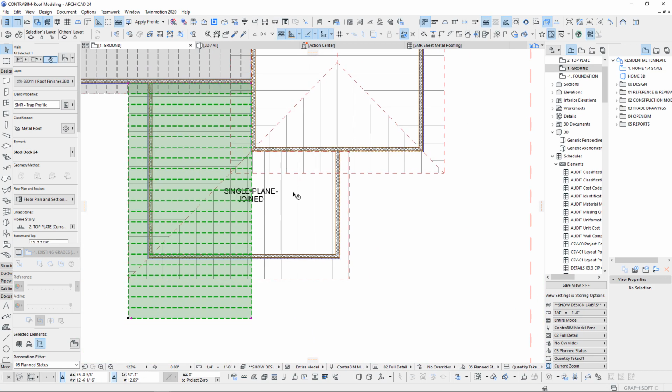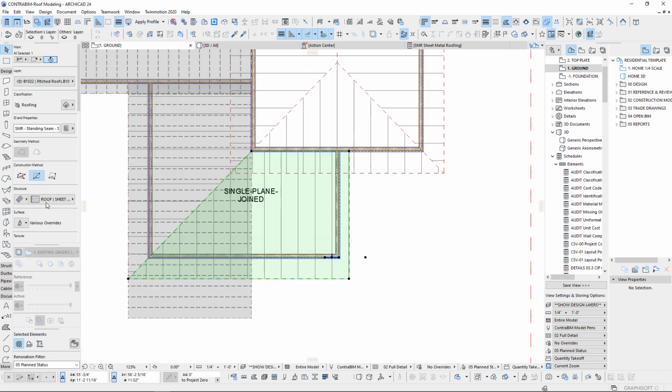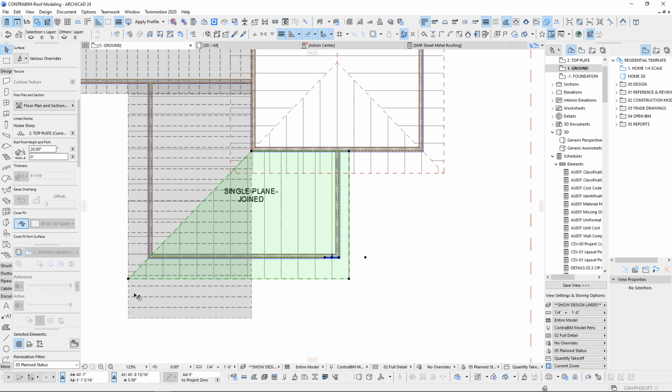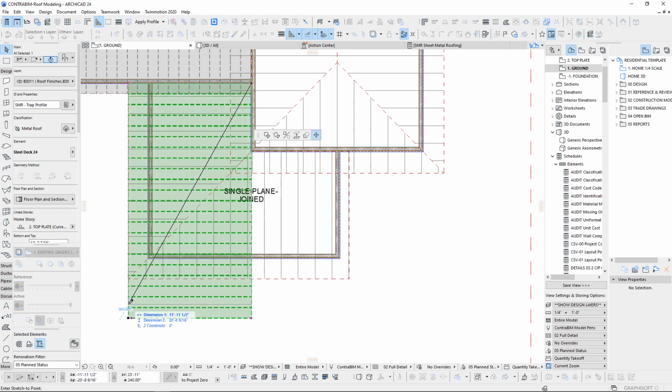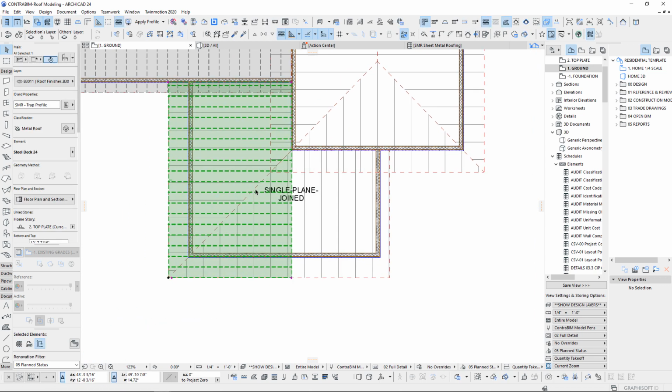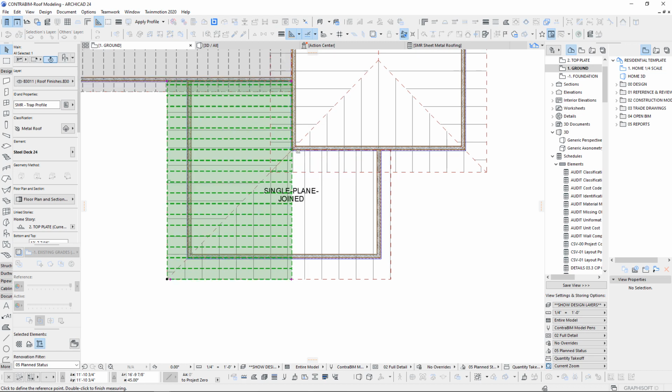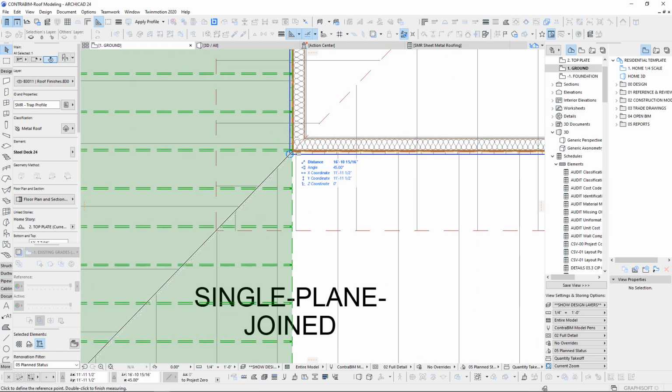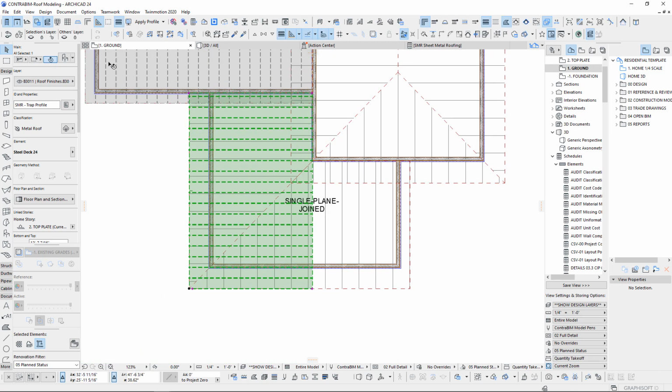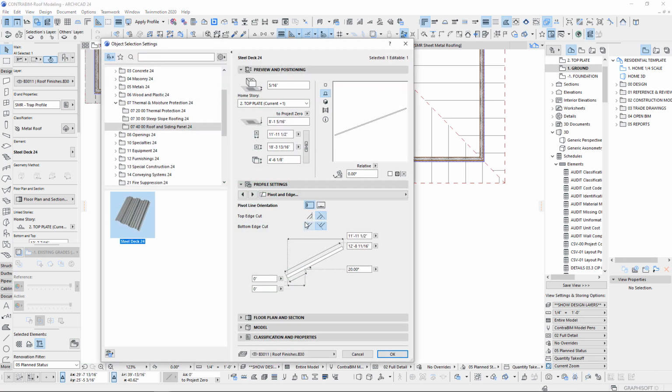We can pick up our roof settings here and just double check. So yeah, 20 degrees. This roof shape will work very well for us as well. And then from here, we can just simply measure to our dimensions here. And we know that in this case, we really want to cut it about 11 foot 11 and 1/2. So I can hit X, copy, and then we'll just want to go in here and make that adjustment.